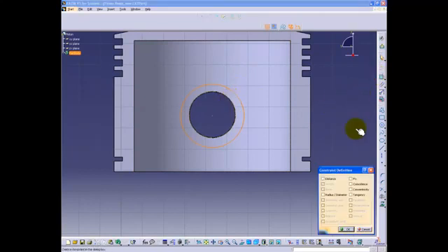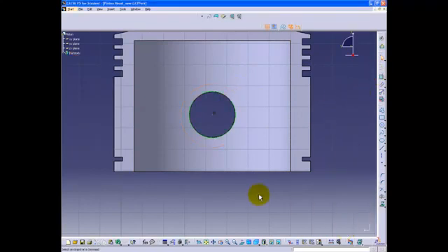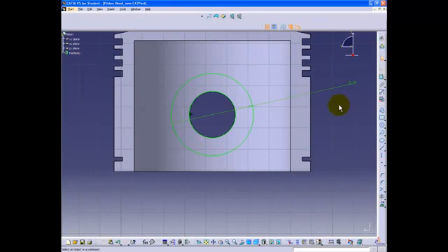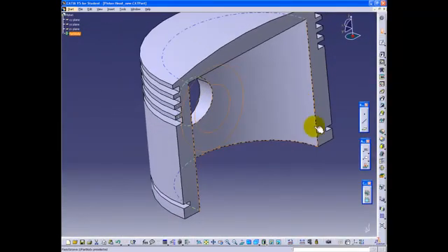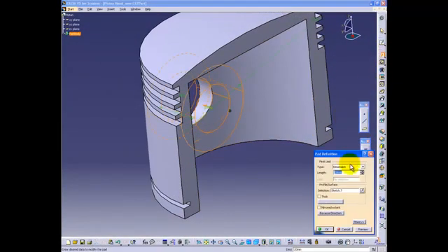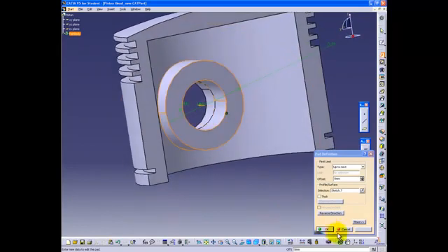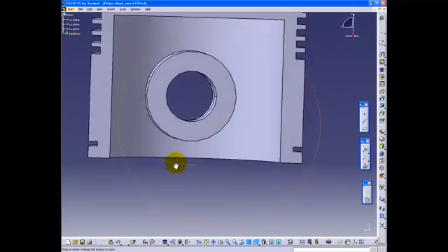Shown here is a common process of creating the required sketch that will be padded. We will now use this sketch in combination with a pad command and select the up to next option. This will effectively force the sketch to mold to the inside surface of the piston without passing the external geometry.